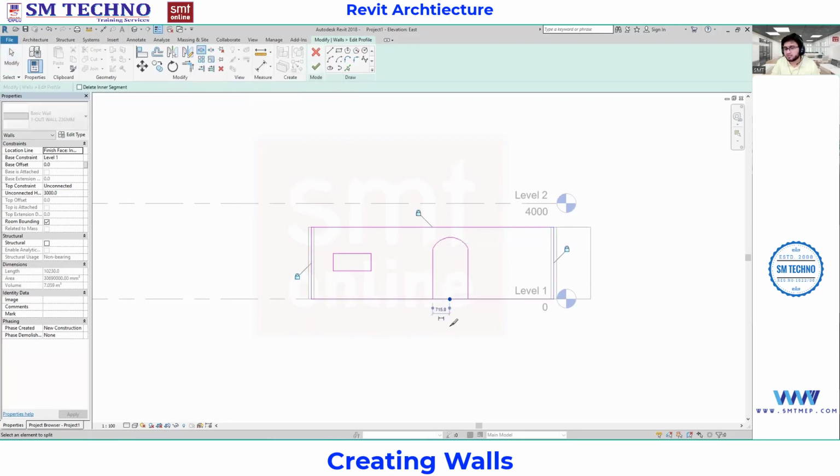Okay, just break the line first. Then again go for the trim option. Trim extend to corner, same like the AutoCAD. So select this line and this line. Again this line with this line. Again this line with this line.